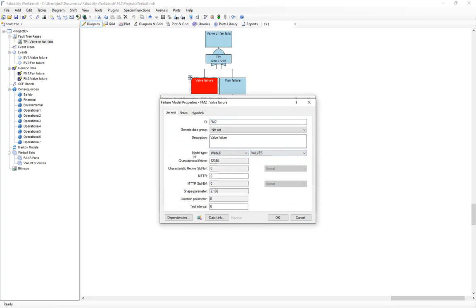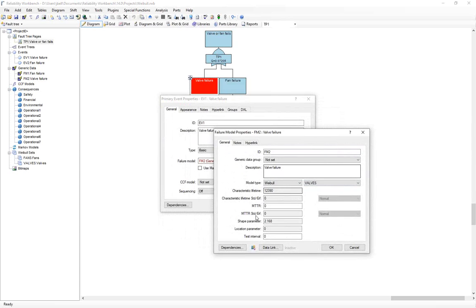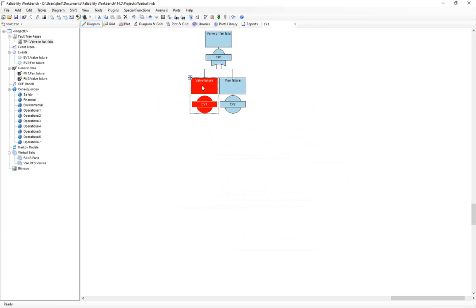So now the failure parameters for the fault tree basic events are inherited from that Weibull data set. In other words, this basic event's failure rate is being quantified from real-world historical failures for that component type. Make sense?